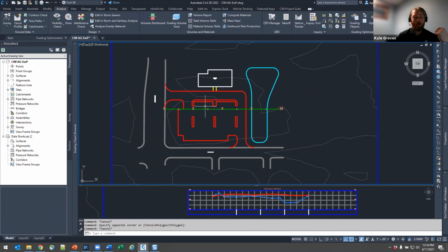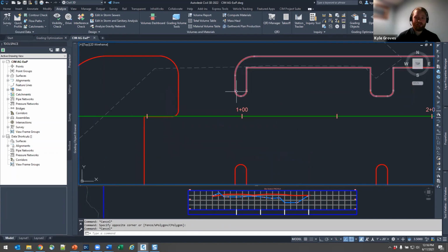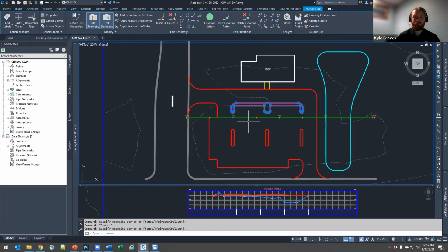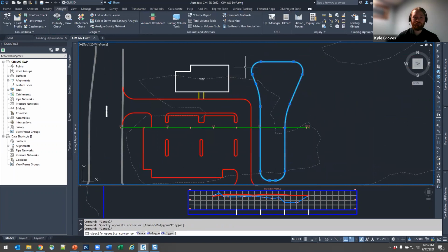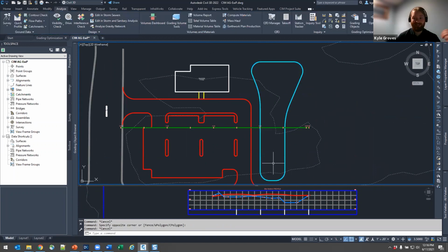So from here, I now need to start creating these other site features. I need to create a 3-dimensional stepped offset series for my curb and gutter. I need to create some inward sloping something for my detention basin. And then in certain areas, I'll also need to go through and daylight back out to my existing conditions.